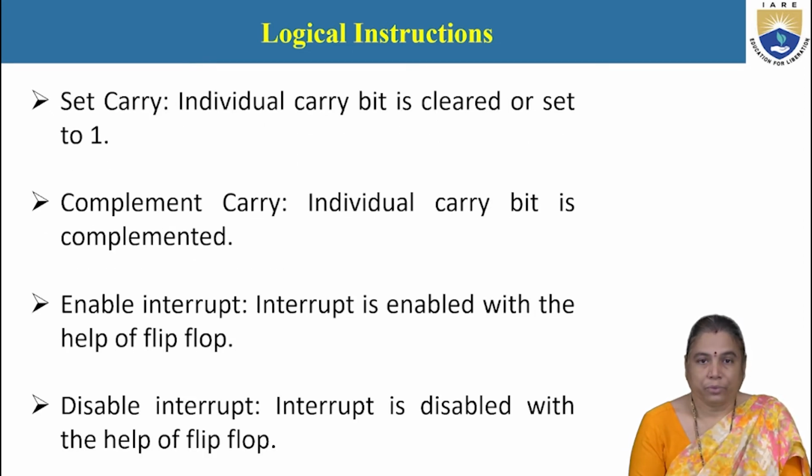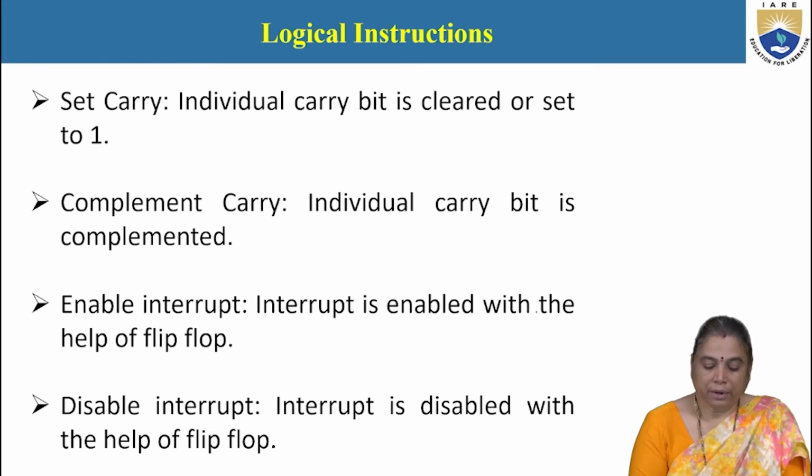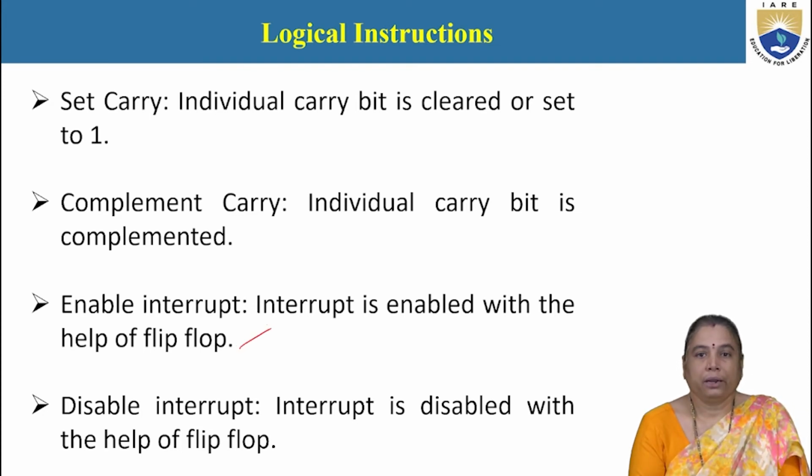Set carry is used to store a one value in the carry bit of the register. Complement carry is used to produce the ones complement of the carry bit. Enable interrupt is used to enable the interrupt with the help of a flip-flop in order to indicate that